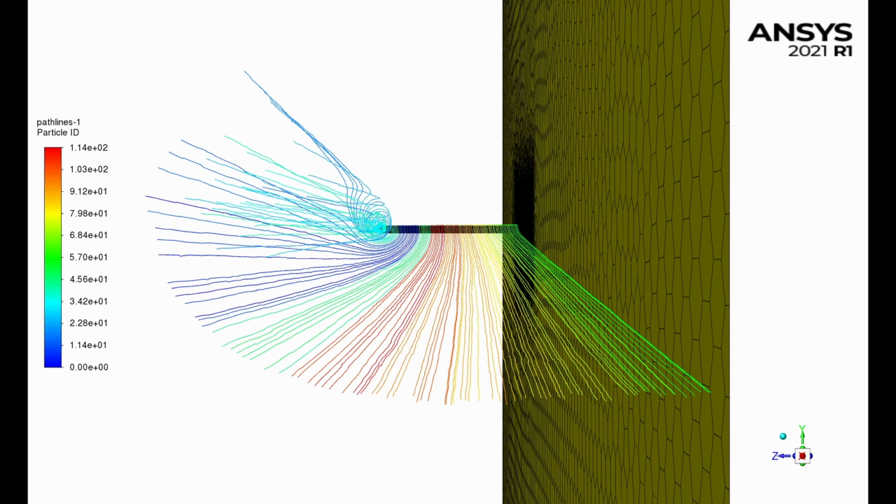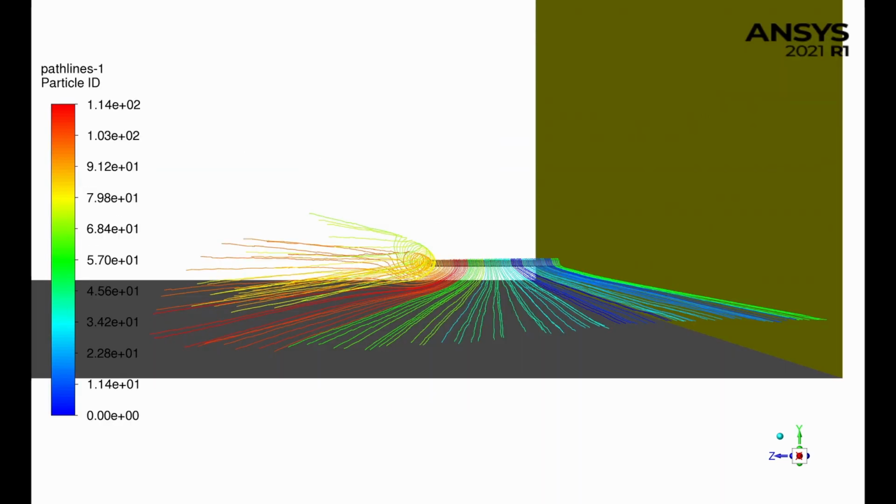And in general, streamlines or path lines that we would normally expect to stay in one plane are lifted out and twisted outside of the plane, meaning our vortex has both a large horizontal and vertical extent. An important thing to note, though, when comparing to the wall case now, is that the path that our vortex core has is mostly parallel to the free stream.